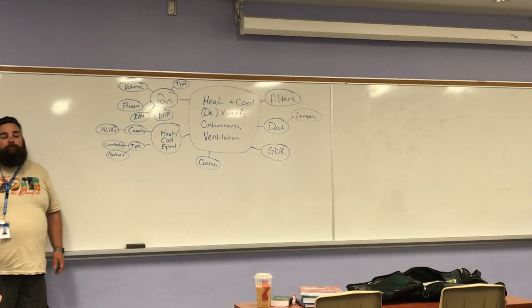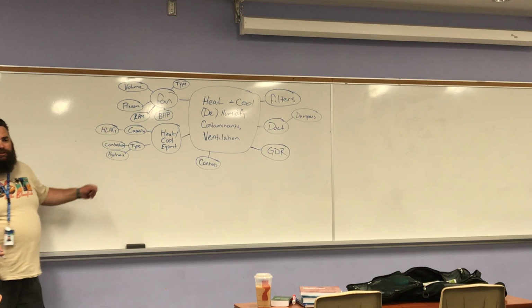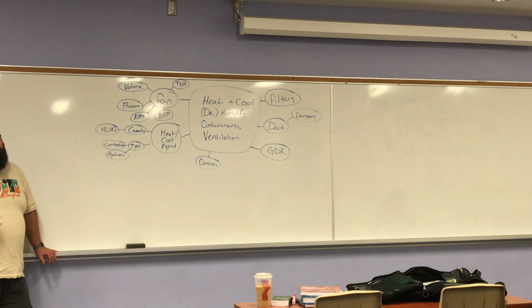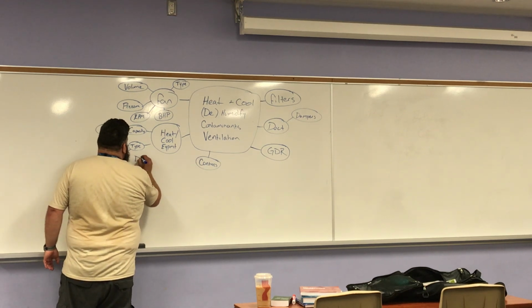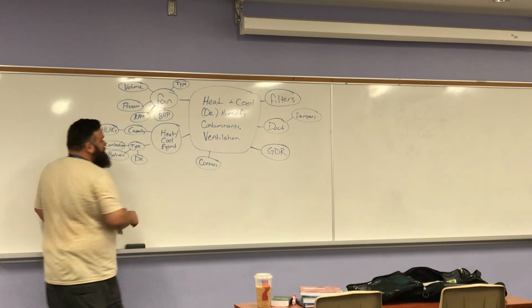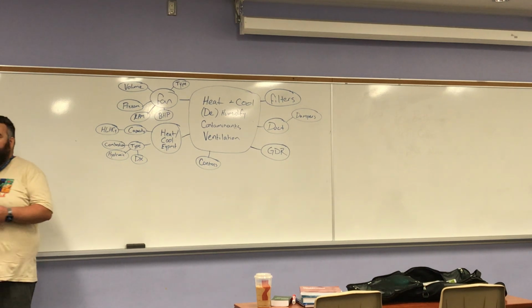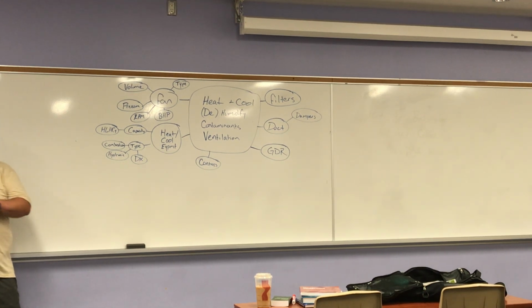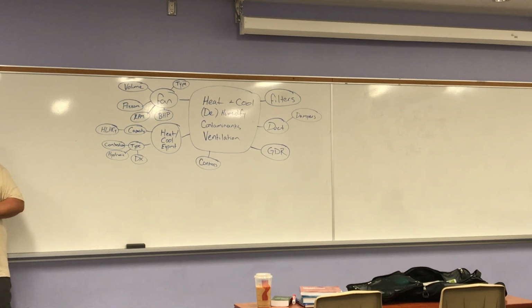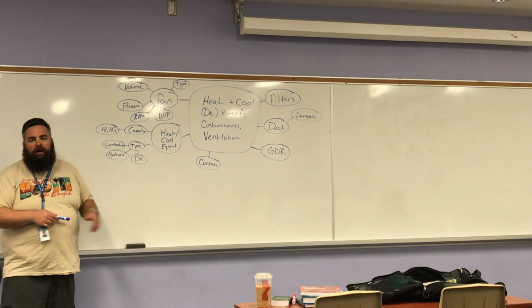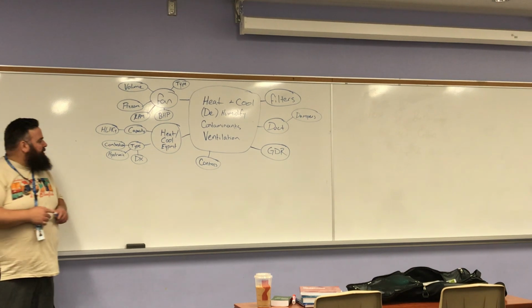What else? Geothermal. Okay, geothermal will branch under hydronic because we're moving water through it. What else? Refrigerant. Yeah, the refrigerant, so I'll put DX. What does DX mean? DX stands for direct expansion. If you think of your refrigeration circuit, when we go past the metering device and that refrigerant flashes and expands, that's what we're talking about. We could also have absorption, like an ammonia chiller, but I'm not going to bother. Let's call it DX. That's good enough.